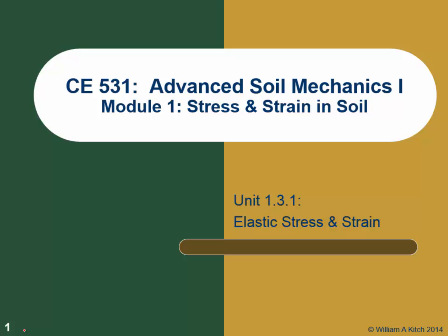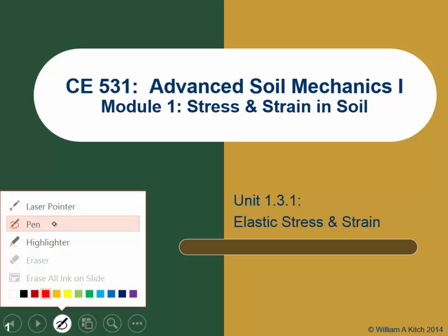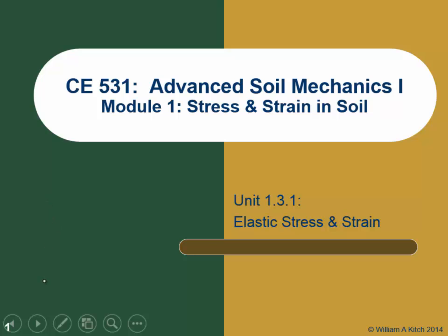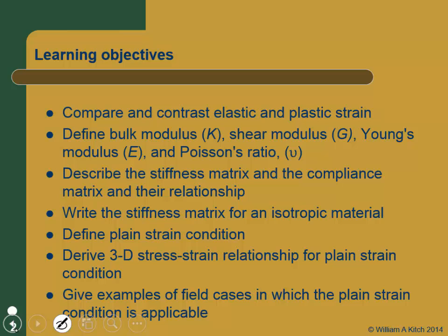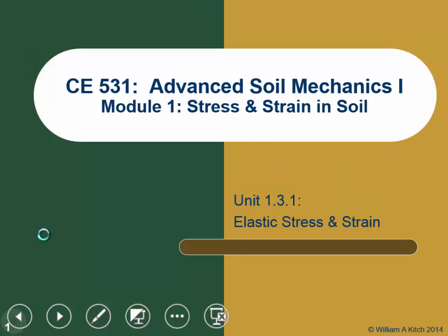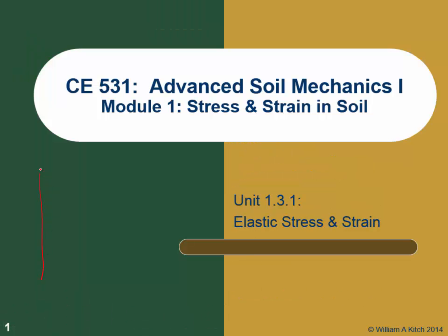So stress and strain. We start off with these E log P curves, right? You all know this, right? Where we tell you, this is going to be log of sigma prime, and this is either the strain or the void ratio. And we say, yeah, this is what the stress-strain curve looks like for soils. You've got C sub C. It's like, all right, that is a really bad thing to do.